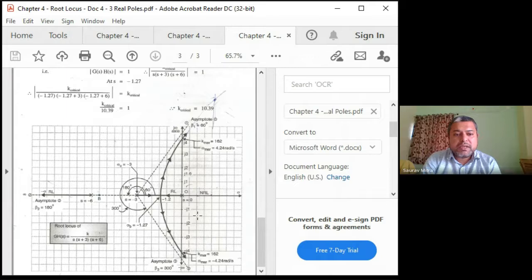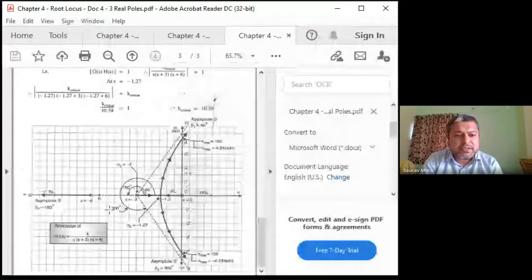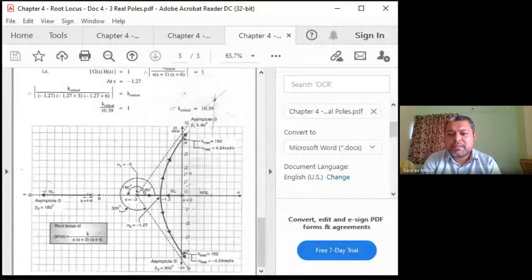So initially the -6 problem is solved, because at k equal to 0, this pole will be at -6. As I am increasing the gain, it will keep on going in the negative side of the S plane. So it will keep on getting stable and stable, an absolutely stable pole. There are two poles which are conditionally stable, or relatively stable, as we call it. What are the poles? Whichever are at 0 and -3 at k equal to 0.